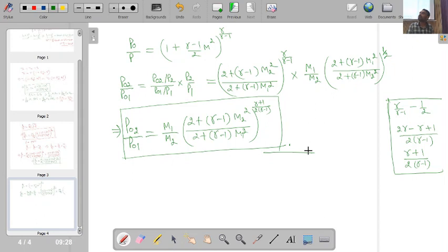So from here we are also able to calculate the value of stagnation pressure. It means that by utilizing all these parameters, if I know Mach number and friction factor, then I will be able to calculate the downstream Mach number M2, and then once downstream Mach number M2 is known, all my parameters like ratio of stagnation pressure, ratio of density, ratio of static pressure and static temperature are involving nothing but M1 and M2. Okay, so if these two parameters are known, I can predict all the values.